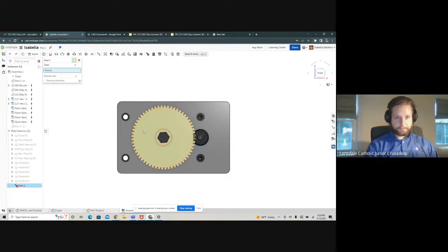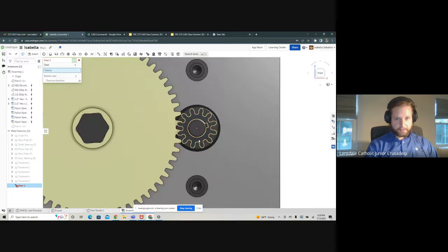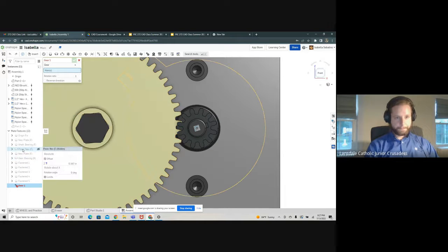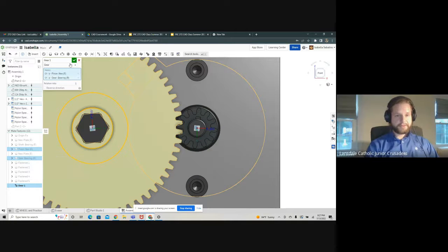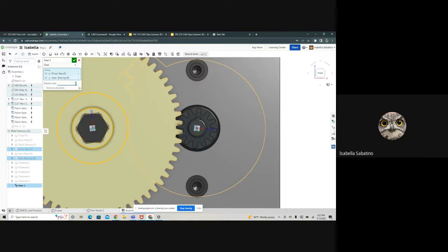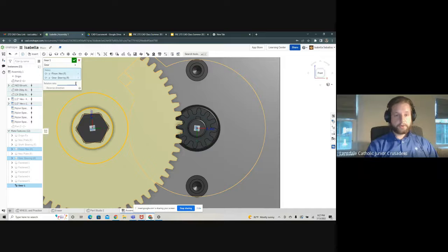So now you select the gear function and then select not the part, but the mate. Yep. The two different revolutes. I labeled these. Very good on the labeling. And then you need to put in the gear ratio between the two, which is 1:1. Oh, that is not a 1-to-1 gear ratio. It's 60 to 12. So I'll just put 5-to-1. Or you could type in 60 divided by 12 if you don't know what the division is for that, because this program does math for us.